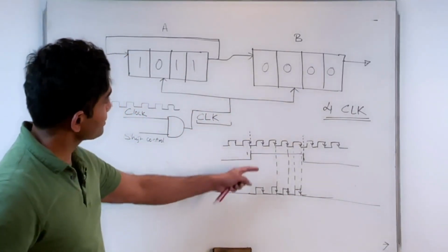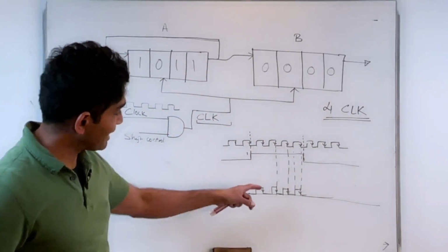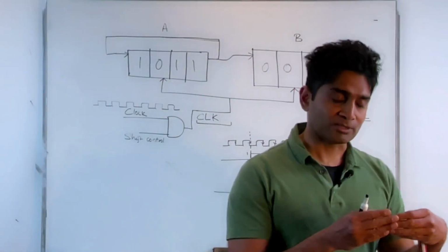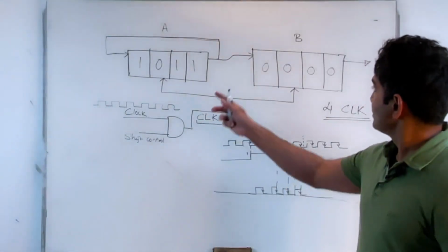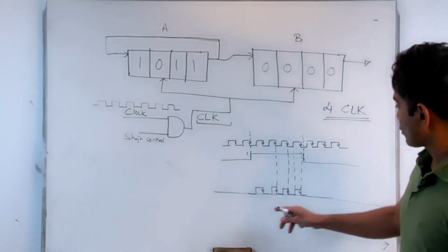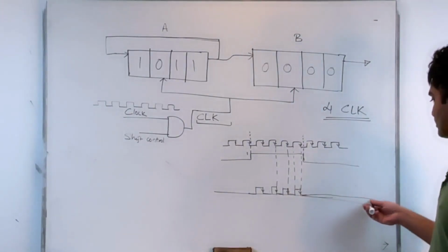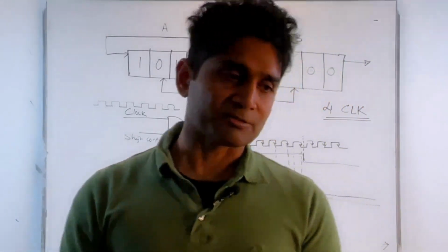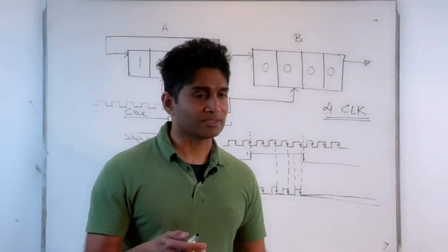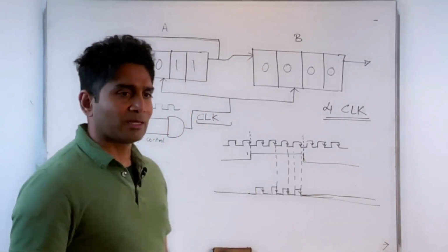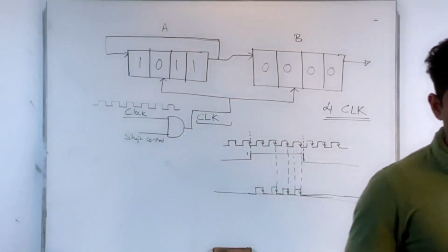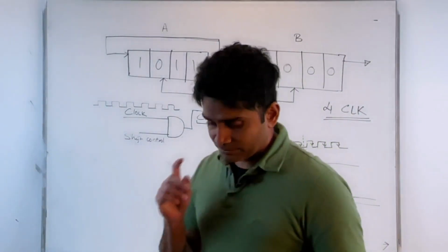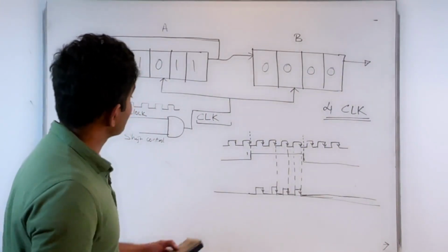In other words, I'm applying exactly 4 clock pulses to my registers, so that once the content is shifted into this register, after the fourth clock pulse, of course, my clock is now disabled. That means I'm no longer shifting the content, and the content is preserved, and that's it. So that's just an example of where you can apply these timing signals for synchronization operations. Okay, all right.